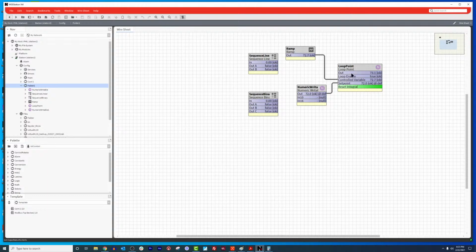As you can see right here, we're accumulating way too fast. We know that we have 25 for our proportional band, so for every degree of error, we should have 25%, but we just shot up to 100% super fast. We should not have that. And that is a key sign of integral issues.